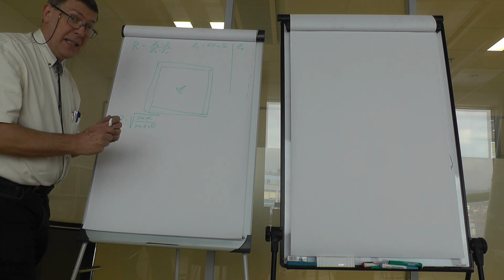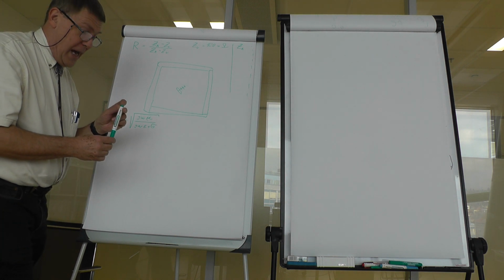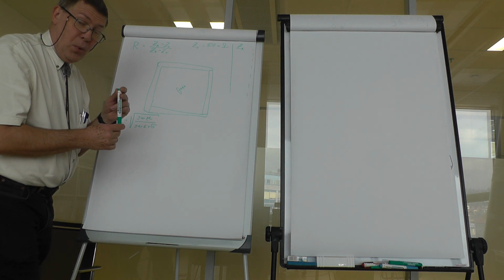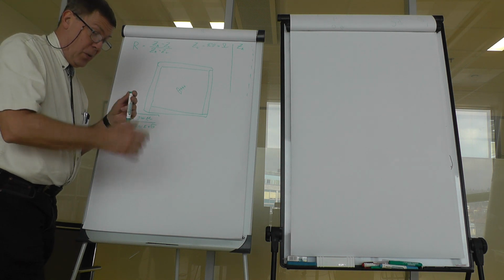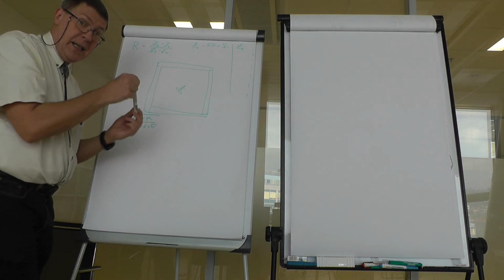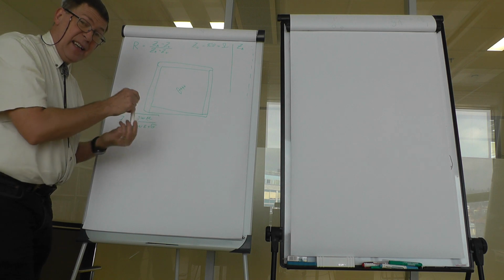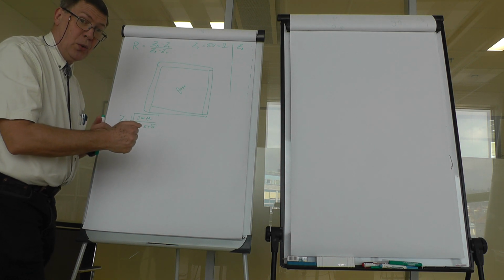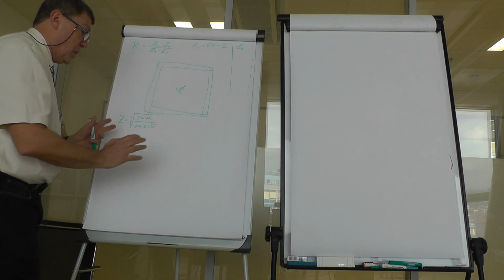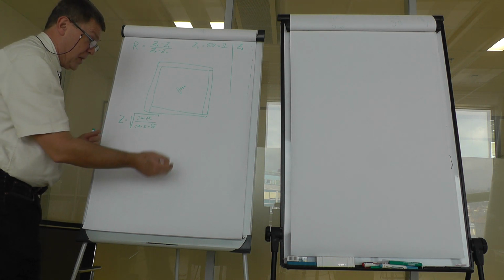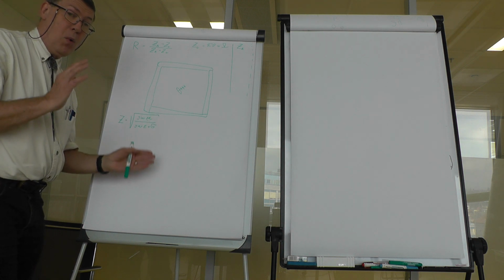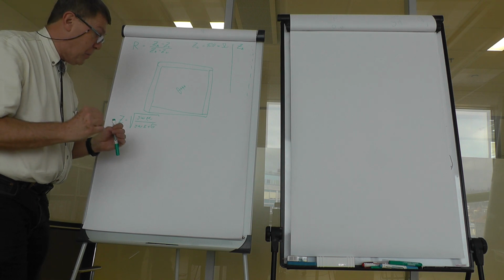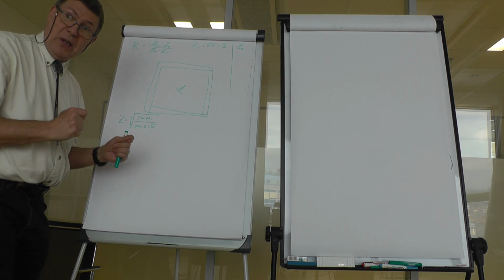But the fact is that the small domains within the glass get polarized by the harmonic wave in opposite directions. And when repolarizing, some part of the energy of the field is converted to heat. But in our model, this is represented by conductivity. So it's more or less a parameter that would create the property, although it's not a real conductivity.